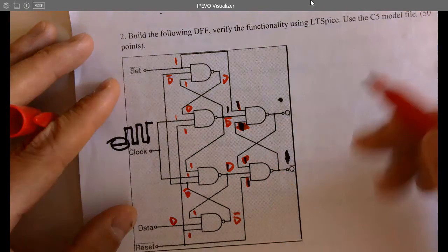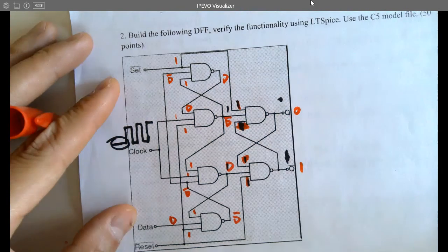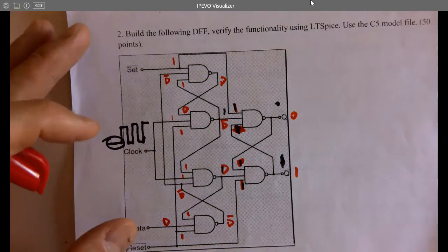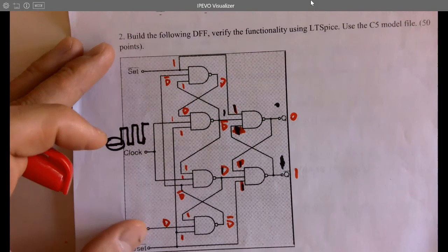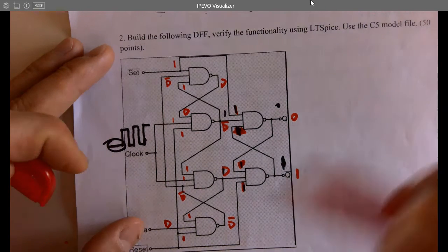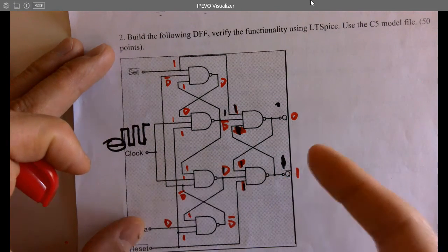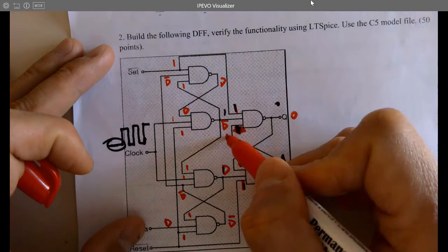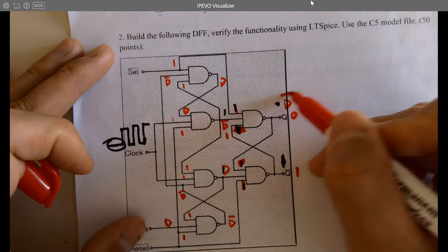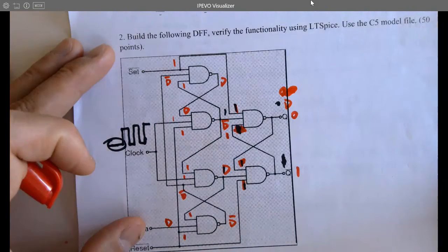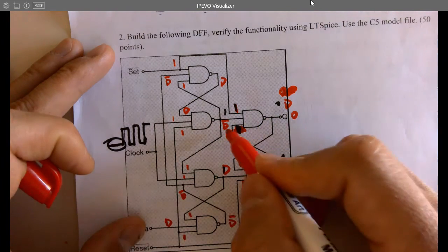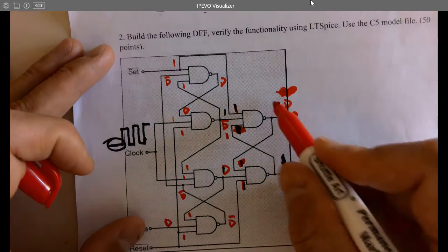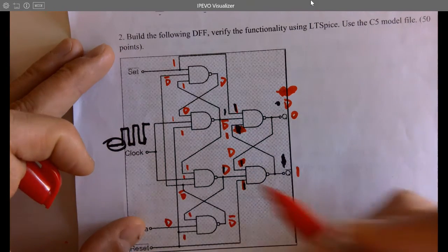No problem. What about the other input? So we need these 2 inputs. Let's give examples. If this was 0 1 at some point before we change the data, okay? If it was 0 1, where should you start with? Keep in mind, start with 0, because 0 will give you a definitive answer here. So 0 comes here, will give you a 1. And 1 will be fed back here, right? So 1 1 D bar are going to give a D. Oh, D. Yeah, D 1 D bar 1, right? So it's going to be a D. So Q is D. Good. What about Q bar? So D will be fed back here. D D 1 will give a D bar, right?